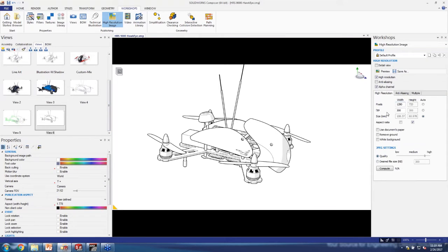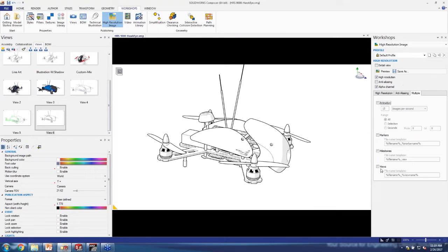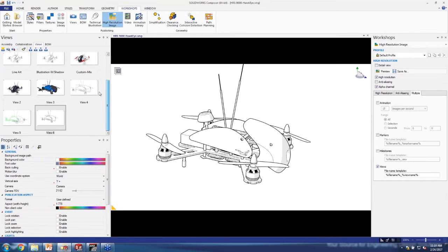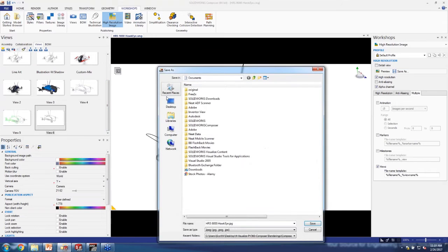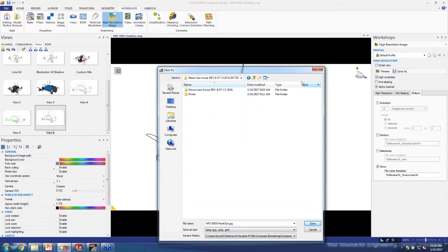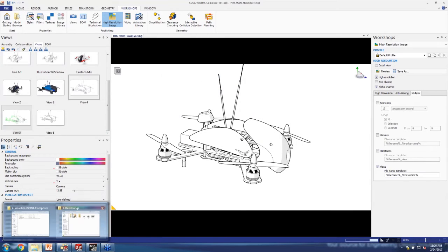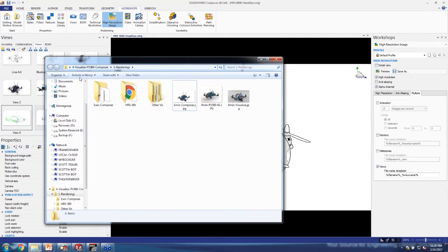However, as you can see, when I'm working in Composer, it's flawless, and we're able to render out fast. I just want to make sure you understood that I'm not on some super powerful workstation that I'm flying through this. It's really the speed of the software on a decent computer. Okay, so we've got 11 renderings. What I'm going to do is specify my resolution. For high resolution, maybe you want to go 600 dpi. We'll set the quality all the way up, and I'm going to say all of the views, so all of these here in one shot. So, 11 renderings, save that out.